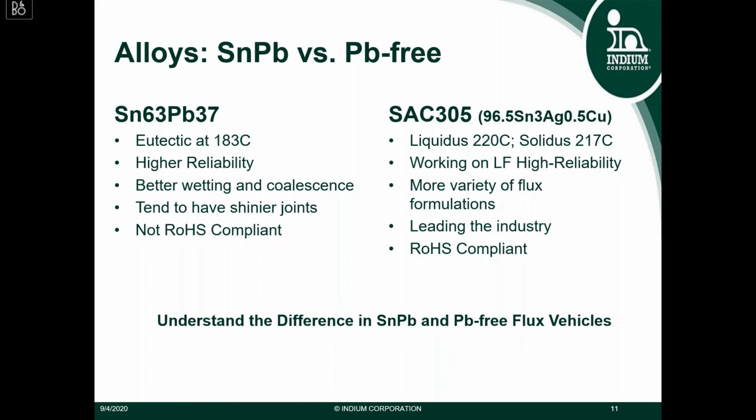Because the industry is moving towards lead-free, there tend to be more variety of flux formulations that are being developed. As of the past couple of years, lead-free has surpassed SN63 or any tin lead combination in the amount of electronics assembly, because it is RoHS compliant. And so to end on a note about how the alloy affects the flux and the solder paste, let's understand the difference between the two flux vehicles for leaded and lead-free solders.